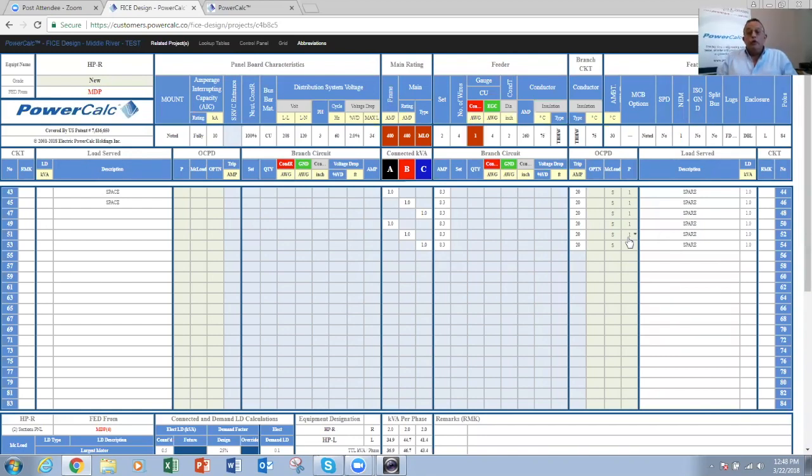The common point between the two ratings is the fault current. So you perform your fault current calculations first, and then based on that value. The short circuit condition, as we talked about last time, is the worst condition that the system will ever experience during a malfunction of a circuit breaker or an accidental contact between two conductors. So if anything catastrophic happened, that's the maximum short circuit current that will pass through the system. The equipment has to be rated to sustain that amount of energy and react, open and clear that fault without any catastrophic damage to these pieces of equipment.